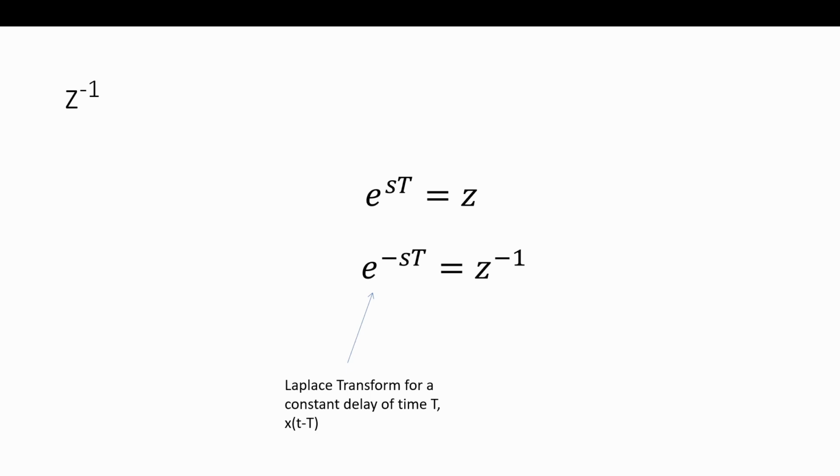So if I had a delay of T samples, the frequency response is e to the minus j omega capital T. What do you observe about that? Again, e to the minus j omega capital T. It's a phase, yeah, and what's the phase dependent on? Yes, it's a phase that's dependent on frequency.